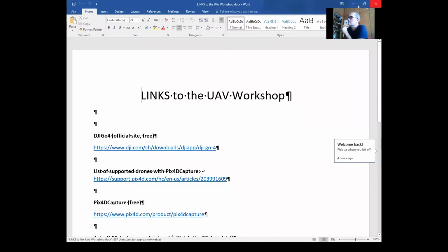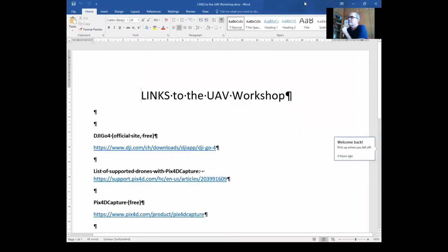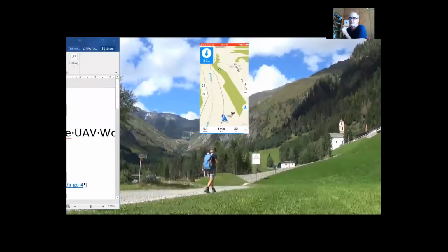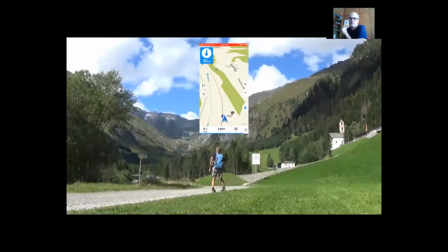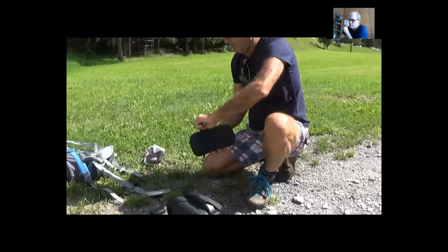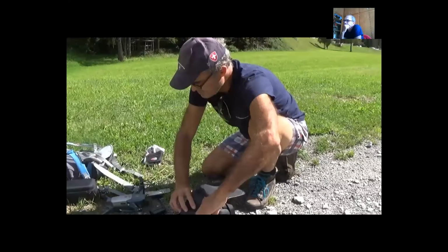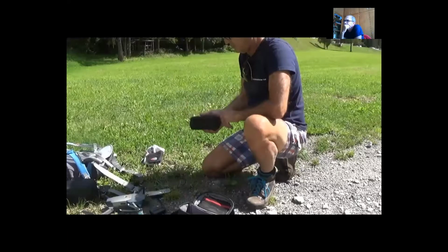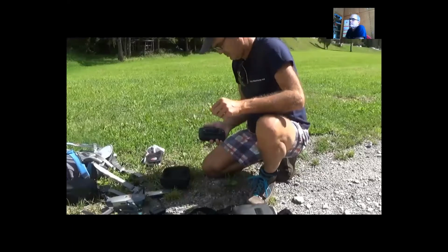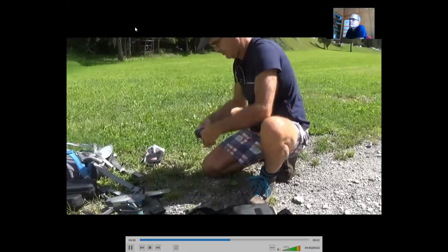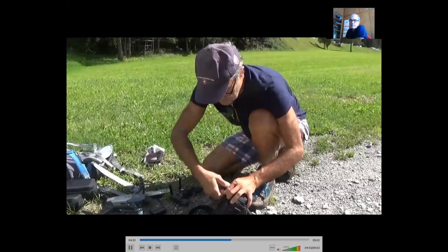Inform the authority before going into the field, eventually send them the flight plan. Ideally, you go on the field with some authority, with a policeman. The drone can be confiscated, or it can even be worse. You can be jailed if you are close to a military zone or close to an army checkpoint. Everything has to be done very, very transparently. Inform as well your office about your plan, and be with some local people in case of need of translation.